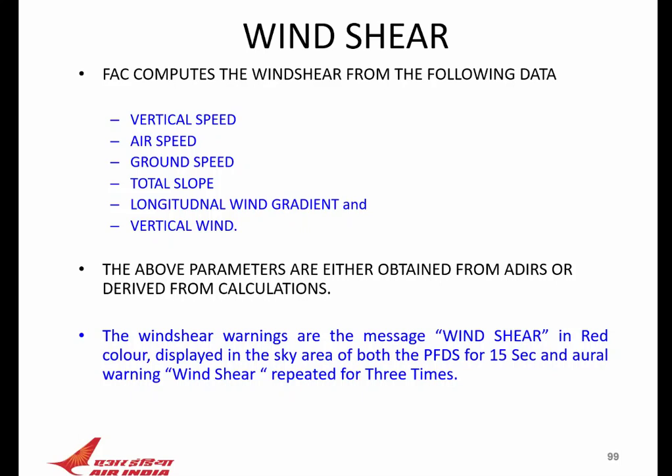FAC will compute the wind shear mainly from the ADIRS. Parameters taken from the ADIRS are the vertical speed, airspeed, ground speed, track slope, longitudinal wind gradient, and vertical wind gradient. All are provided by the ADIRS. Warnings are: the synthetic sound will come, wind shear, for 15 seconds. A 15 second wind shear warning will come.